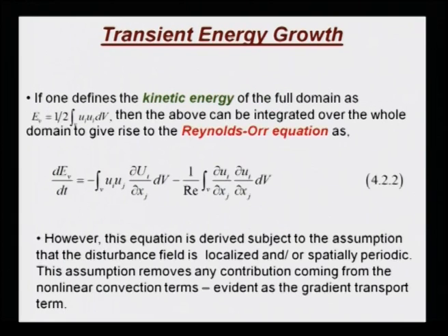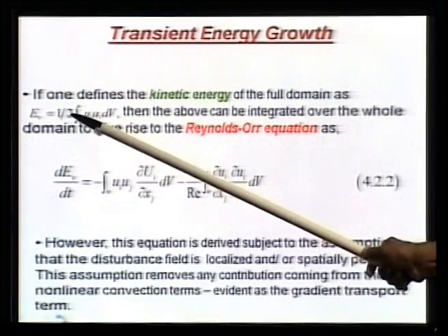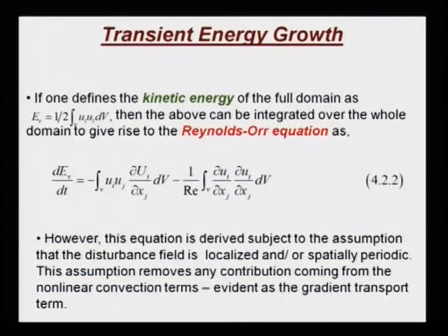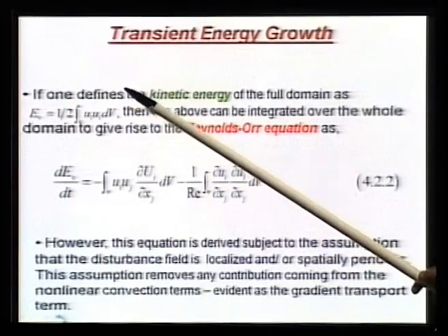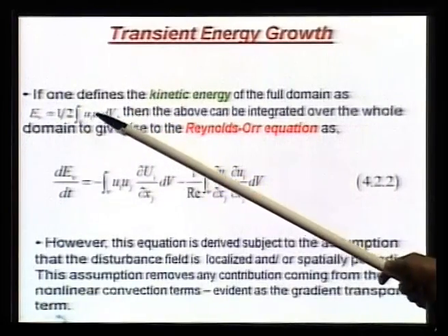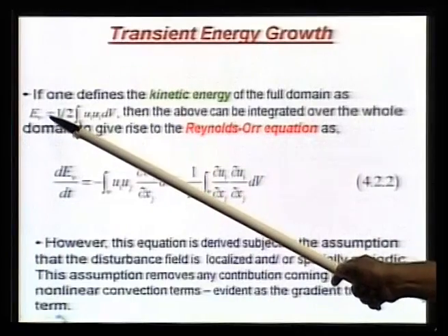In particular, you would be interested in a particular quantity, the kinetic energy, which is also a second moment, but which is nothing but half of u_i squared. So, if I write down the second moment matrix, these are the sum of the trace of that matrix, right, half of u squared plus v squared plus w squared, integrated over the whole domain; call that E subscript v.